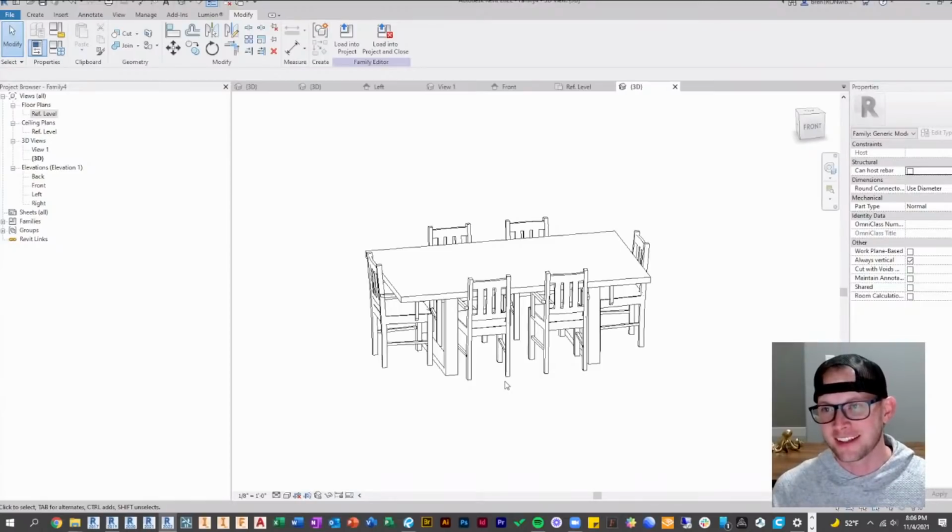Yeah. It was tempting because here's the thing. What I had to do to fix it was take the hardware out. I thought I was being clever because not only was the drawer a family, but the panel on the drawer, because a drawer essentially is a panel with a back and then hardware. I also was using that panel family like on a kitchen sink where it's just a blank panel. So I was doing it to make it easier to build for me, but it was a nightmare to use. So what I had to do was make it a nightmare for me to build, but now it operates much faster. But for me to build them, it takes a lot longer now.